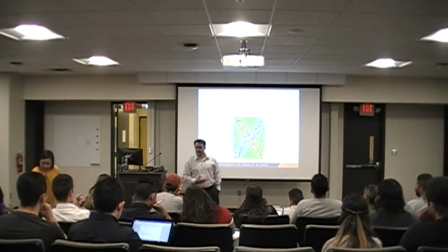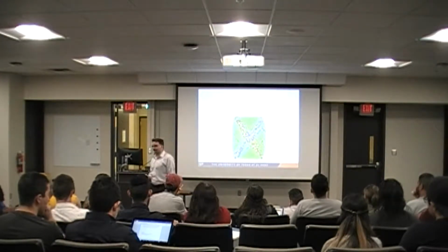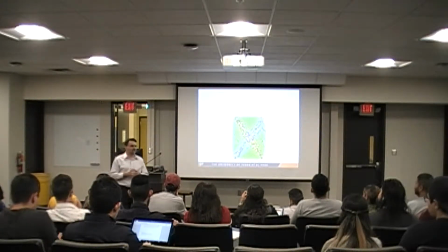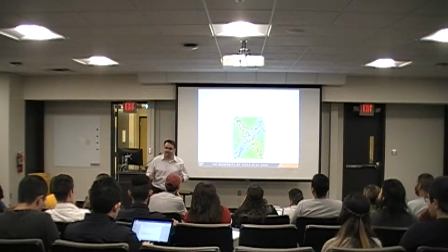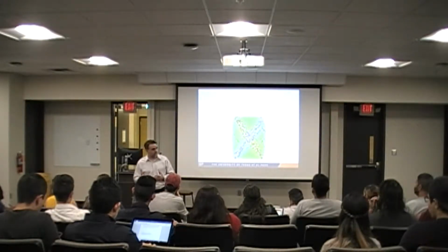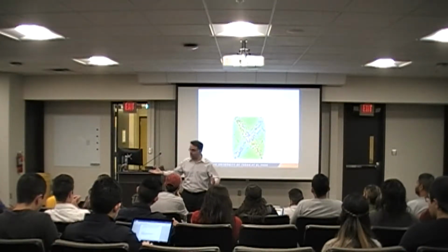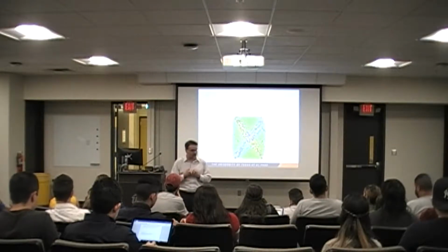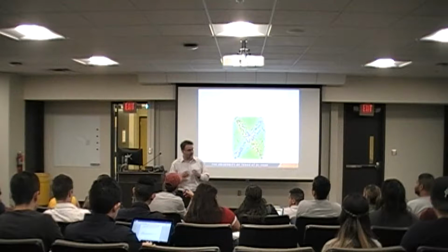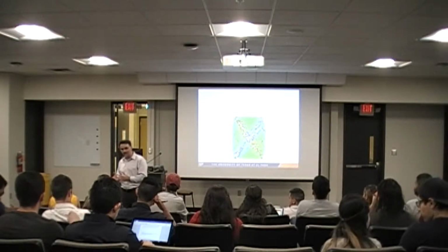How about for soils? For soils, it would be a different story. Can I put soil in tension? Remember what the load transfer mechanism was. The load transfer mechanism in particulate soils was related to friction, right? So you're looking at the interaction of the particles. If I subject the material to tension, you basically will compromise the interparticle contact, and therefore you don't see any strength in that material.